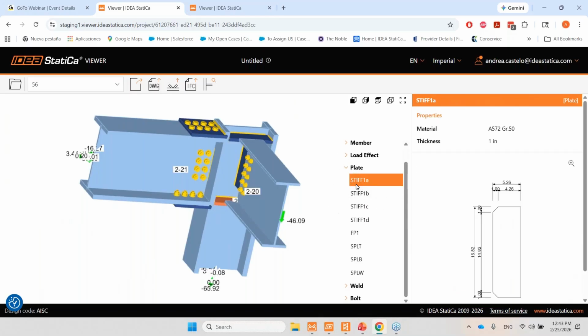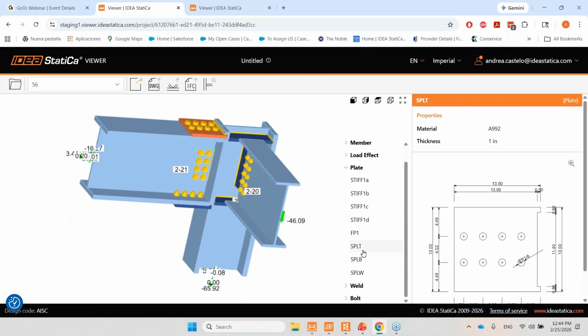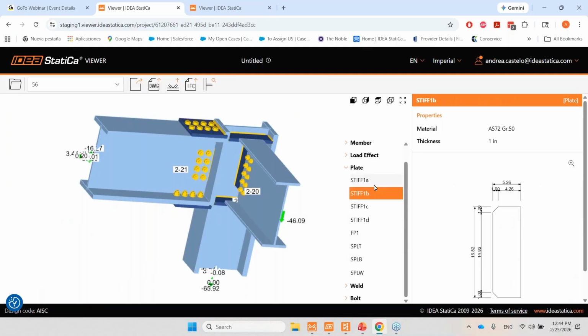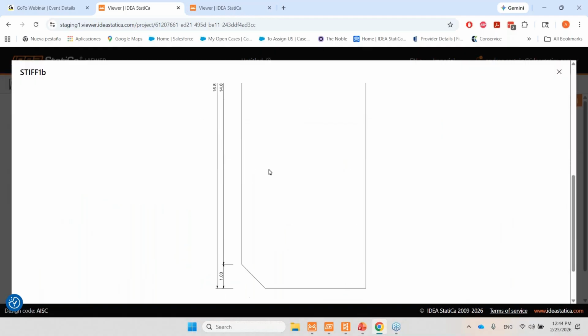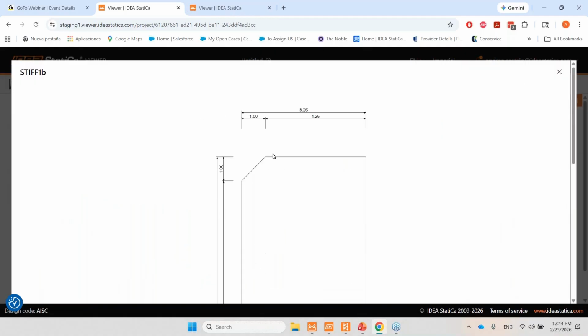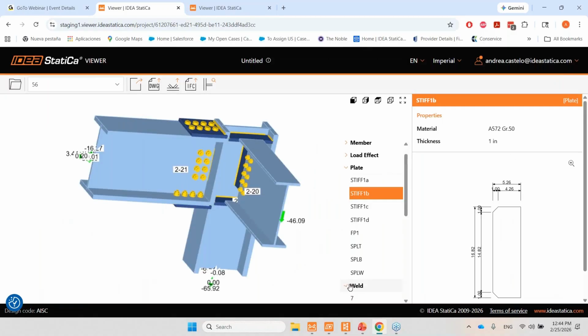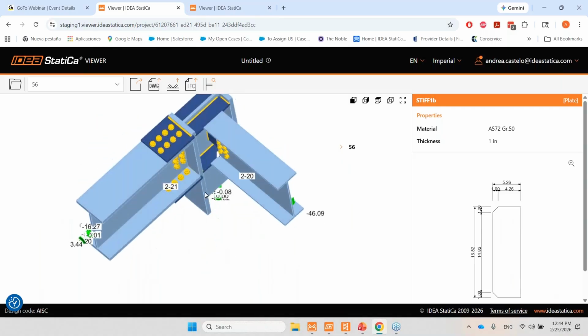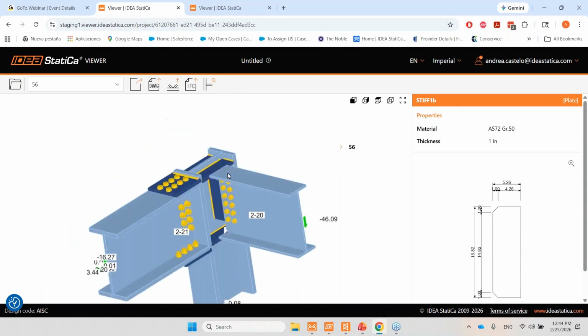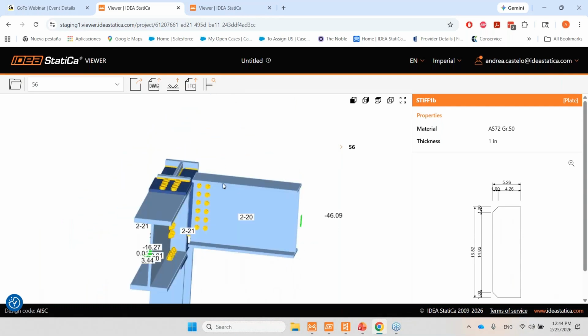You will see the list of blades that were used, and then you can click over the plus icon, and this will generate this drawing. You also see all different details about this connection from this drop-down menu. This is really useful to share with someone who is just reviewing the connection, and they have this way to visually review the connection.